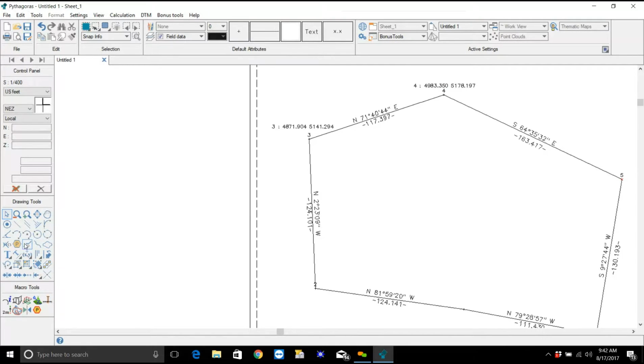One more thing to show you on this video. You see this tool over here? This is the Polygon Tool. And when I click on this and come over here, I can select any of these lines. And what it's going to do is it's going to find all the lines attached to that line, and then it's going to make a polygon out of those. So watch what happens when I click on the line. So you notice I have the little blue line inside. It has now created a polygon as an object out of this whole entire area.